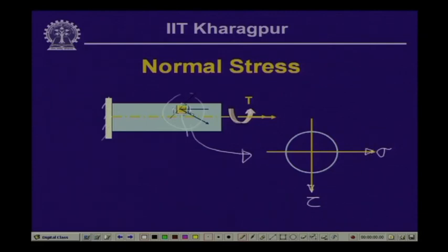Here, as we have designated earlier, the shearing stress acting on this element, according to our convention, is negative, as this shear along with its complementary shear is making a moment in the clockwise direction, which is negative. So, on this axis it is represented by this point, whereas the shear on the other plane is positive, which is making a counterclockwise moment. This is represented by this particular point.